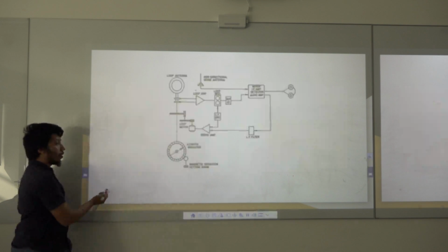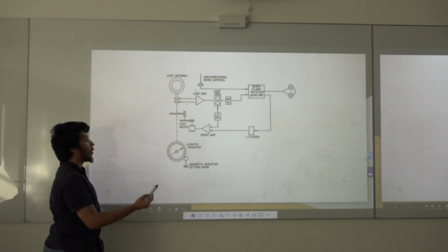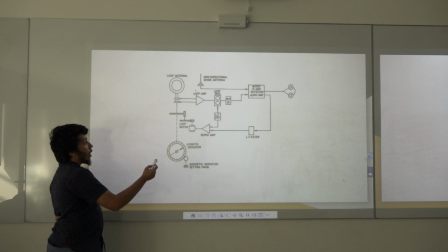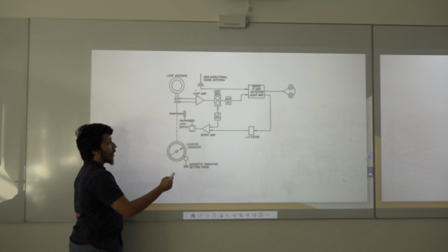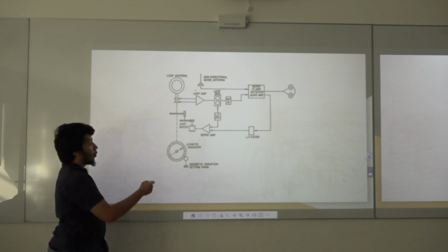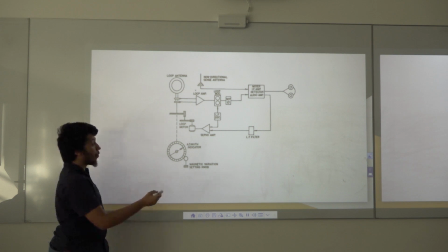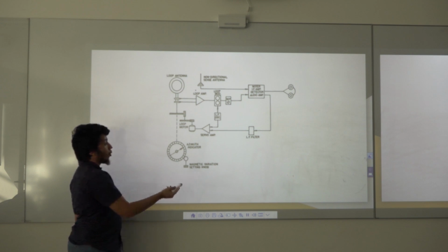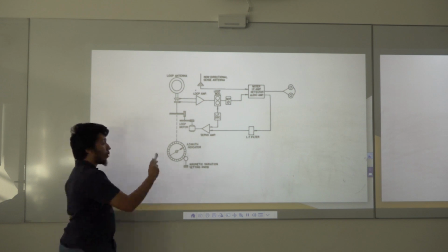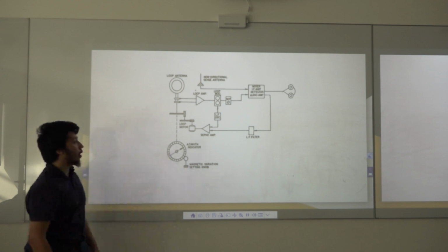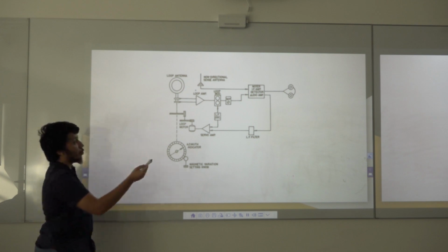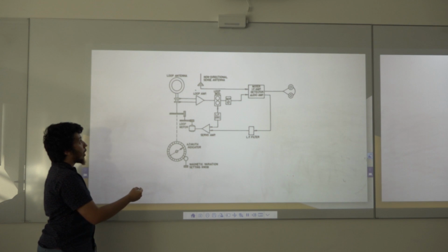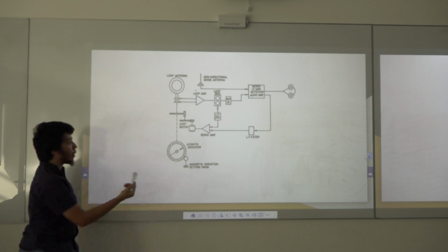This system is purely analog and consists of two loop antennas whose magnitudes are taken and put through an amplifier. The received signal drives a DC motor which turns an indicator. Once this signal goes to zero, at the position where the loop is pointing perpendicular to the direction of the beacon, the indicator will also be perpendicular to that direction and point directly at the beacon, where the port may be. This system also uses a sense antenna to get rid of some ambiguity in the direction and uses it as a reference for the amplifier as well.